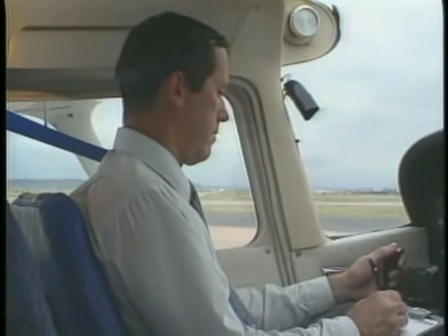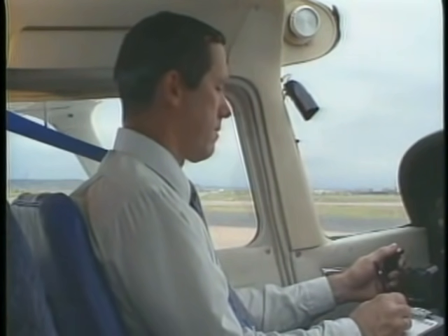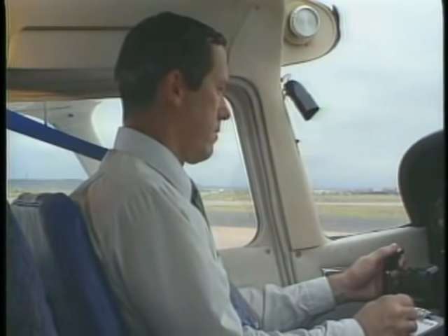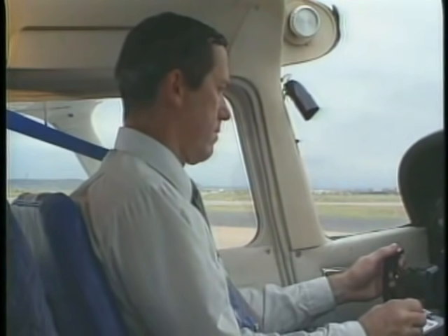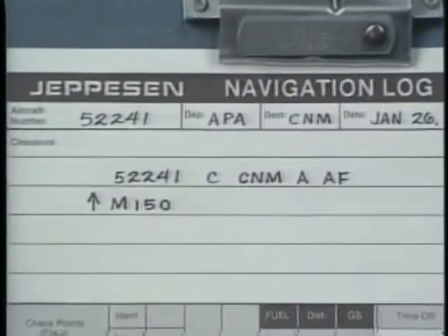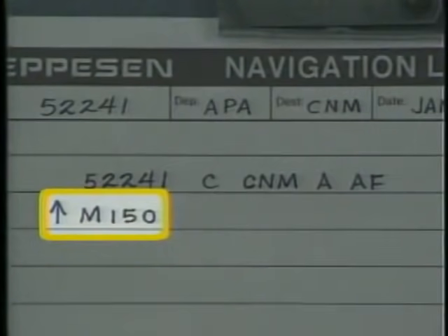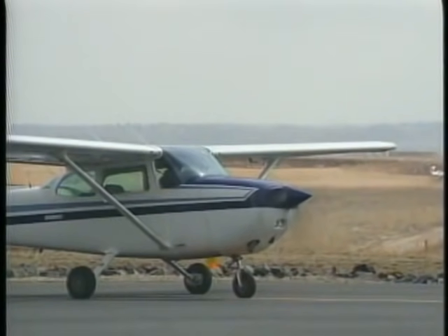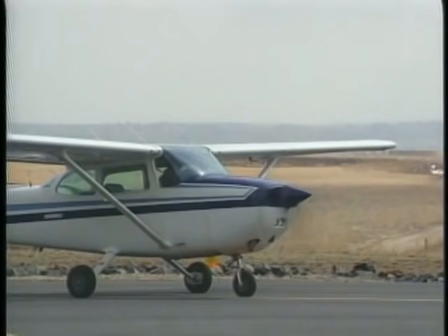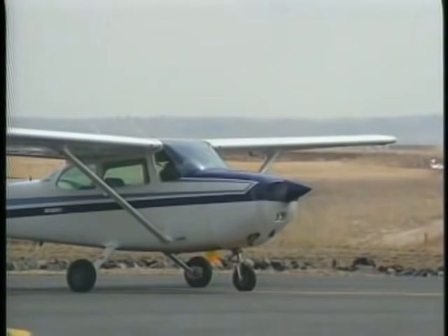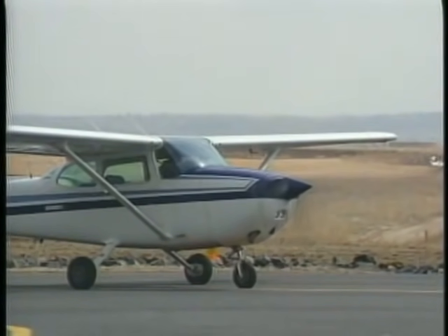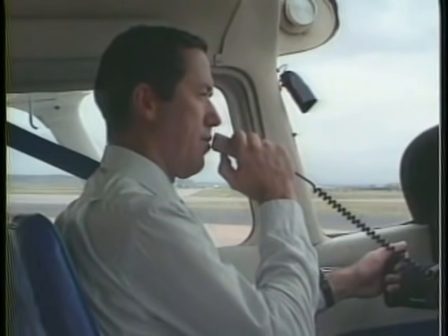Therefore, if it's apparent that the clearance will, in some way, jeopardize the safety of your flight, you should request an amendment. For example, let's say that you receive these instructions before you take off. Cleared to the Carlsbad Airport as filed. Climb and maintain 15,000. Your aircraft, however, is not equipped with supplemental oxygen, making the proposed flight at 15,000 feet unsafe and illegal in a non-pressurized aircraft. In this case, you need to request an amendment to your altitude prior to departure.